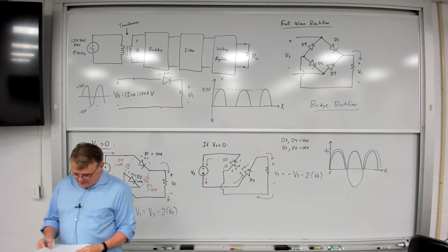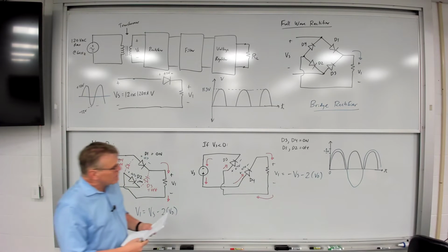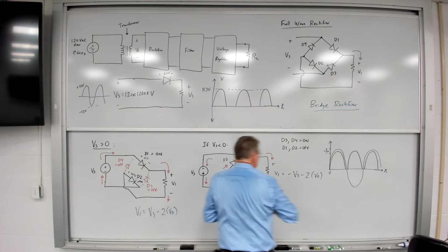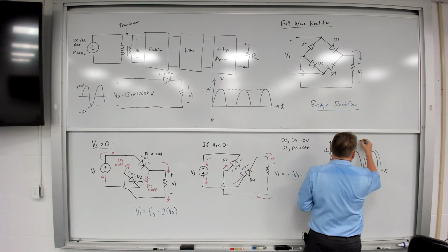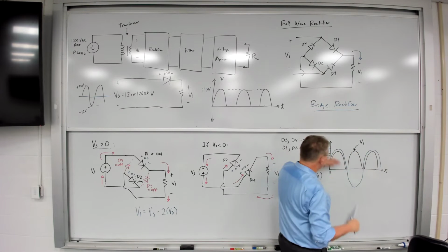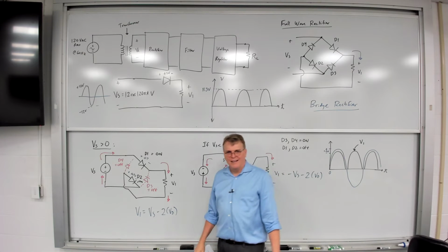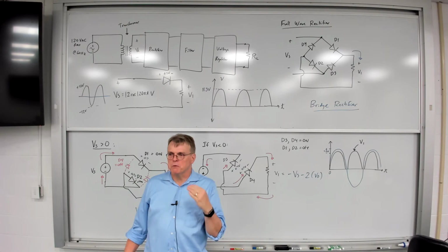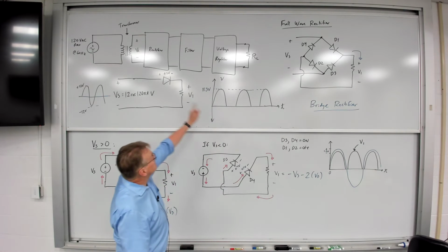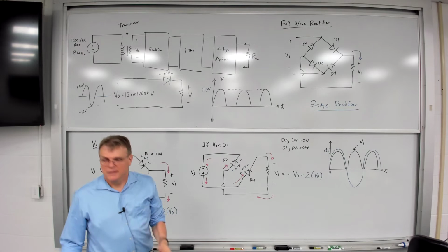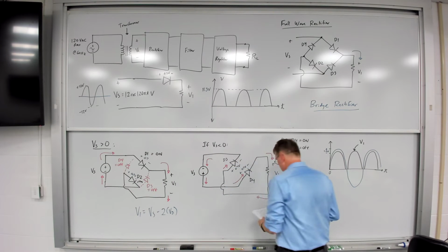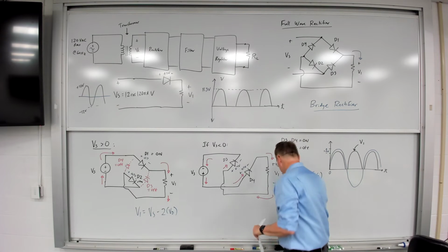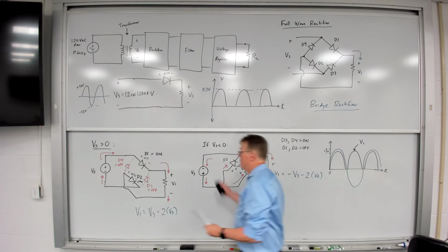Here's our circuit. Now I've got a voltage, V1, which, as you can see here, is all of the same polarity. The only problem is it's not a constant voltage. I want a voltage that's constant. I want to turn this into a DC voltage, a voltage that's invariant with respect to time. So the next step is the filter. Let's take this and add a filter capacitor in order to stabilize our output. And I'm going to do that like so.